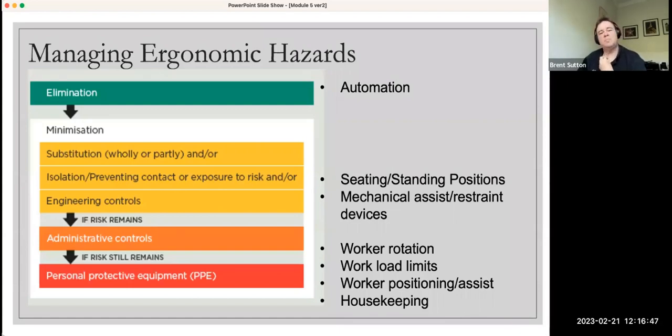In other words, the person can only access that part of that machine from this given location, and that given location has been designed for that purpose. So for instance, if someone needs to do an inspection, then we have a portal or a hatch that prevents someone from straining or reaching in.